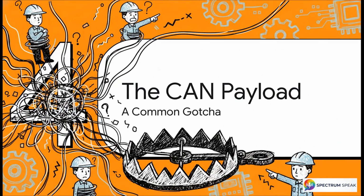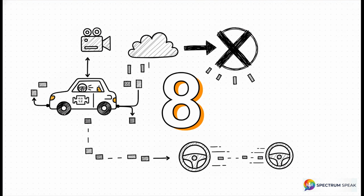Section 4. The CAN Payload Gotcha. All right, pay attention, because here is the exact trap that catches so many young engineers when designing high data systems. The number 8. A standard CAN frame has a maximum payload of exactly 8 bytes of data. That's bytes, folks, not megabytes, not kilobytes. 8. Individual bytes. This constantly trips up engineers who are used to massive, modern Ethernet data pipes.